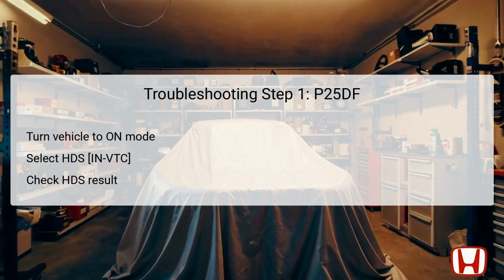If the HDS reports an OK status, this indicates that there may not be a malfunction in the VTC system at that moment. However, if it indicates not OK, this signals a duplication of the failure, necessitating further investigation into the VTC components and their connections.